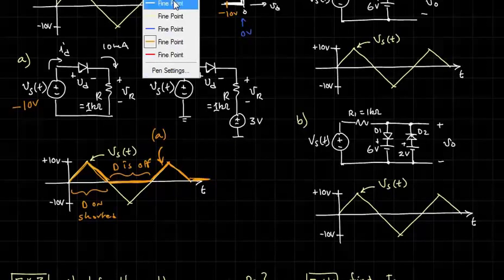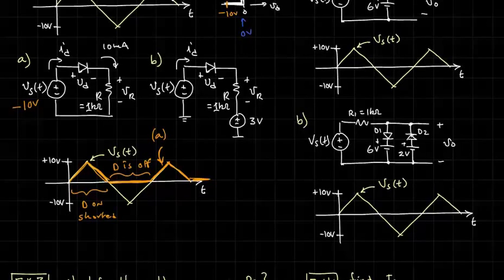Incidentally, if we were to resolve this, but assumed a 0.7 volt drop diode, I won't explain it here, but with a little thought it should become apparent that the shape of this curve would be shifted down by 0.7 volts.